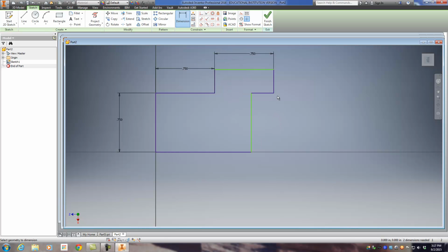And this is where it gets kind of crazy, you know. So that's the only bad part about doing it this way, because then kind of like all your lines get nuts. So you can always hit escape if you need to, and cancel out of that tool. Notice nothing's active, and you can just click and drag those lines out a little bit if you want to. So D on the keyboard again, so it brings up my dimensions. Click here, 0.75.